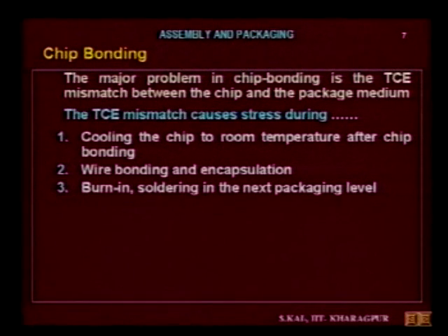The next chance of stress formation is during wire bonding and encapsulation. Wire bonding, I mentioned, is done using thermocompression, ball bonding or ultrasonic wire bonding. There also the temperature of the chip increases, and when it cools down to room temperature, stress may develop.